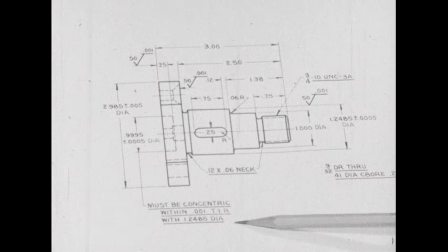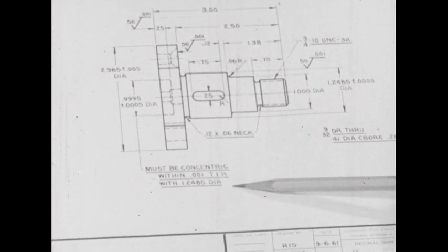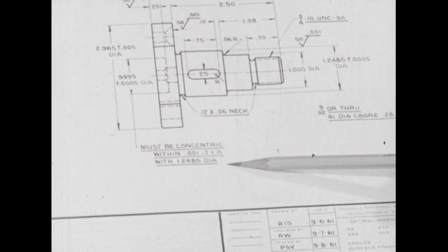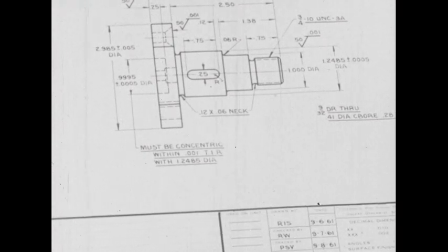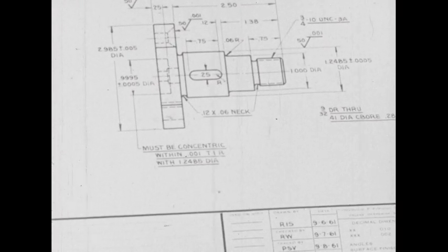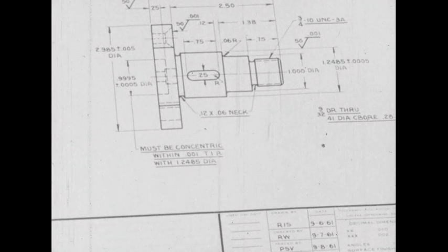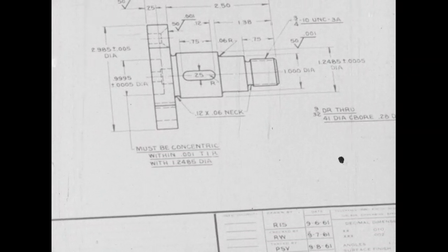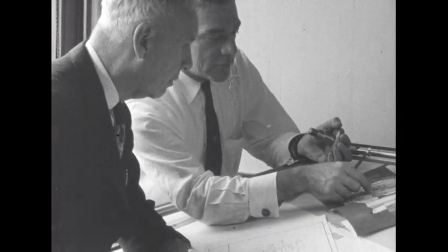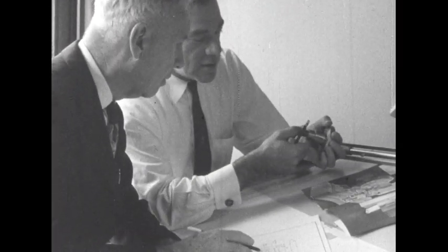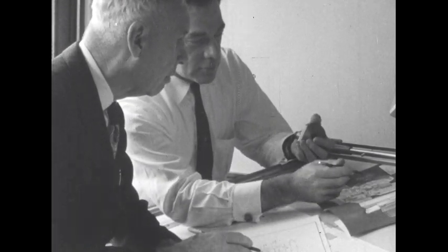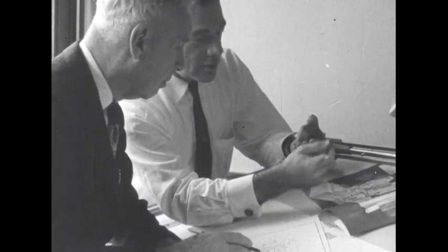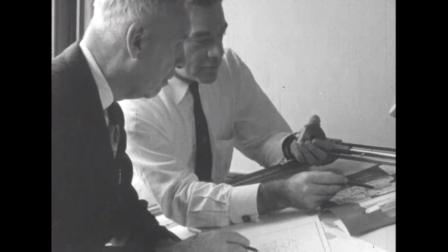Without this note, the degree of required concentricity would be unknown, which might result in an unacceptable part. The engineer inserted the note because his calculations showed that the specified concentricity is necessary for correct functioning. But to accomplish the concentricity, a separate and rather expensive operation is required, as will be shown. This balancing of expense against performance is at the core of almost all engineering decisions. It requires knowledge of the factors behind the expense as well as the factors which affect performance.